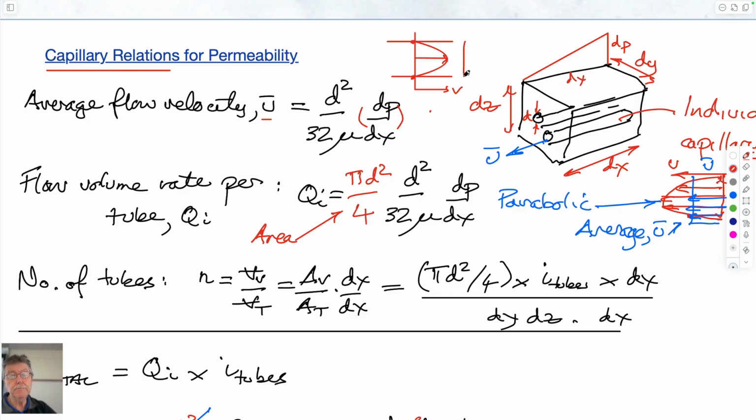And if you take this distribution and you get the area under that curve and convert it to an average velocity, what we're calling u, this area here is exactly equal to this area here. So this is an average velocity that's represented. So I guess you could also do it by taking the total volume coming out of this round tube with time, dividing by the total area of this round tube, would give you the average velocity.